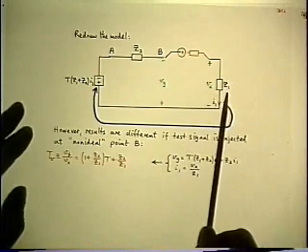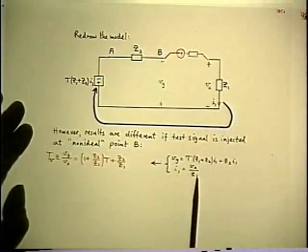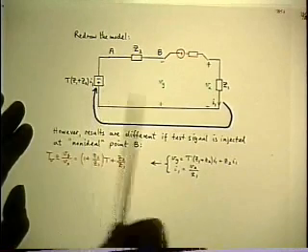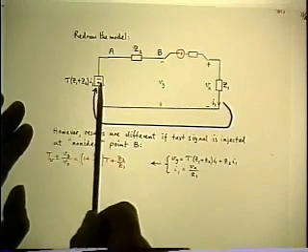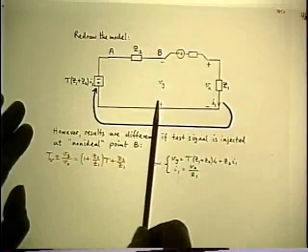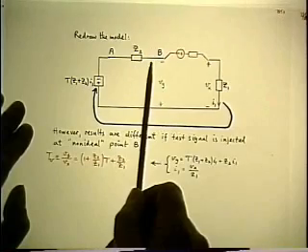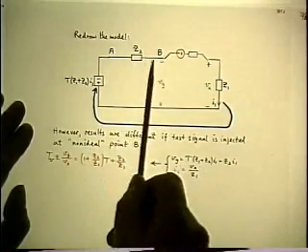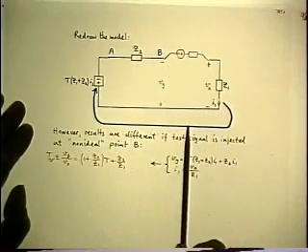Well, that's a very simple problem to work out. I1 is Vx over Z1. That activates this generator. So I substitute for I1 Vx over Z1. But the value of that generator is no longer Vy. I have to allow for the drop in Z2. So I know the current in Z2, it's also Vx over Z1 because it's the same loop current.